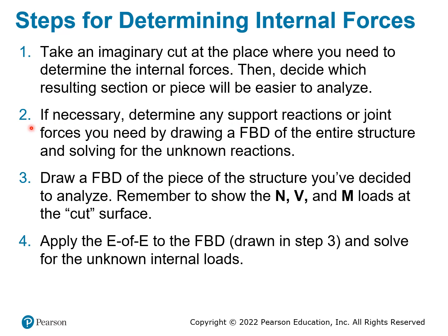And if you don't know the supporting reactions, you should use the entire structure free body diagram to find the supporting forces. This normally is the first step. When you look at the structure, normally they would not give you the supporting reactions, so you have to use step 2 to draw the entire body and find the supporting reactions at the joints.